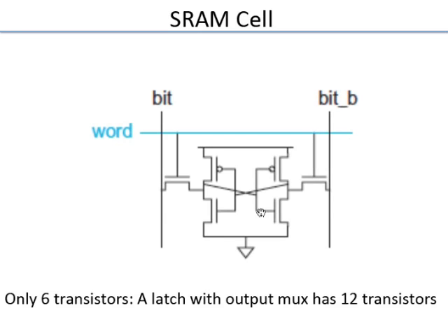And a lot of engineering goes on to optimize the size, layout, everything of these transistors. Certain design rules, layout rules are also bent to accommodate the SRAM, so that the SRAM size is made as tiny as possible. Because if you take modern chips now, pretty much the bulk of the area is spent for memory. You have logic, maybe processors, various hardware engines, and then most of it is memory. And memories are usually SRAMs, but now we have emerging technology such as embedded DRAMs coming up, but largely they are SRAMs. So people have spent a lot of time optimizing the circuit of the SRAM and its layout. So layout is also very important.